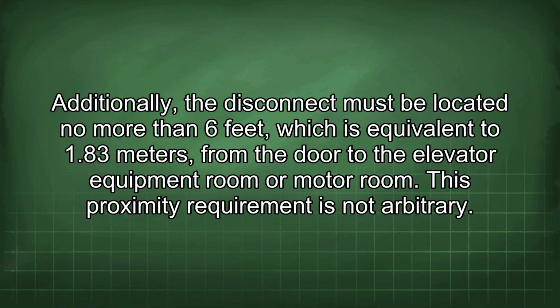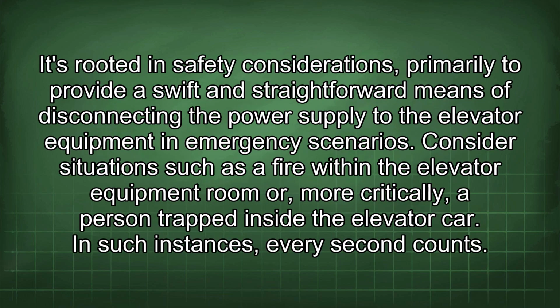This proximity requirement is not arbitrary. It's rooted in safety considerations, primarily to provide a swift and straightforward means of disconnecting the power supply to the elevator equipment in emergency scenarios. Consider situations such as a fire within the elevator equipment room or, more critically, a person trapped inside the elevator car. In such instances, every second counts.